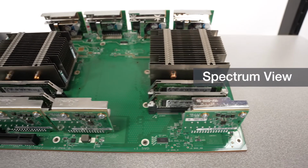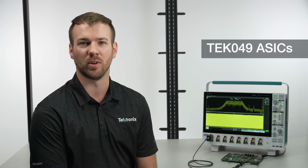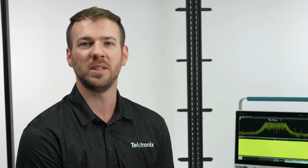Spectrum View uses patented hardware built into the analog-to-digital converter, which we call the TEK49 ASIC. Inside the TEK49 ASICs are digital down converters, which optimize analysis based on the selected center frequency and span settings. This analysis is a more computationally efficient way to display the spectral content of the signal, enabling best-in-class analysis and measurement results. This technology gives you the ability to independently control the acquisition settings for the time domain and for the frequency domain.